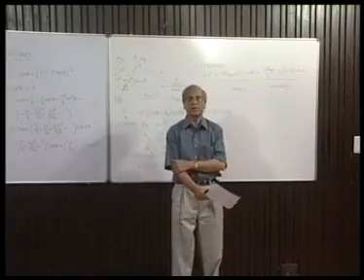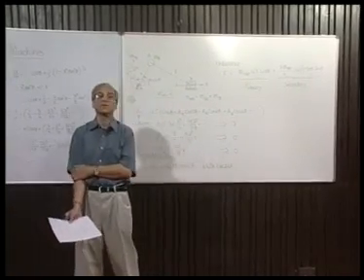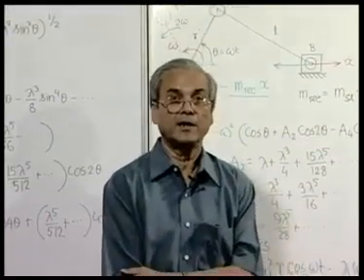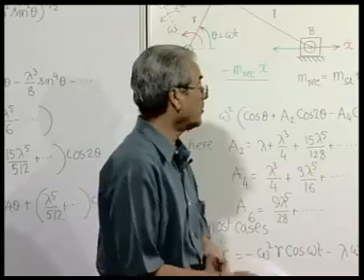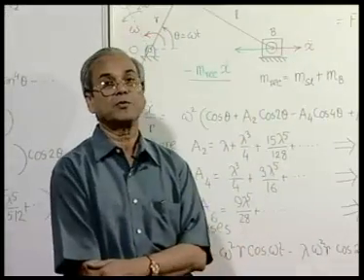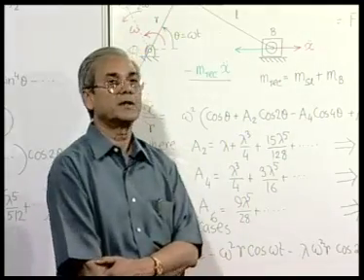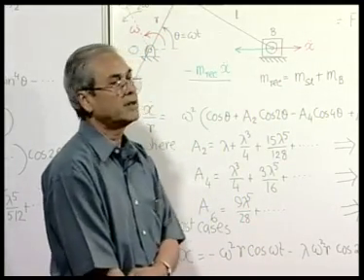We will need to consider the higher harmonics when the speeds of operation are much higher, when the accuracy desired is much higher. For example, the aero engines and such cases, there of course, it will be essential for us to consider the higher harmonics, but otherwise in most of the situations of engines and machines, we do not go beyond this secondary component.